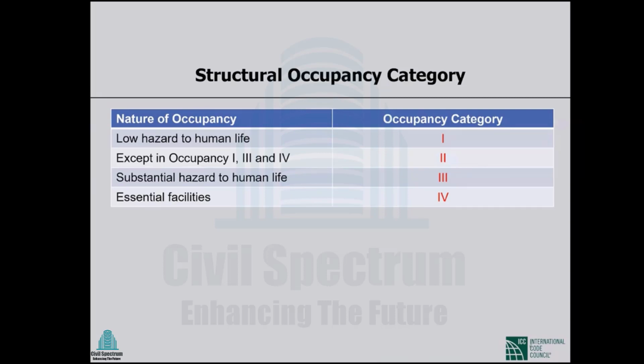For structural design purposes, the most important categorization is this, although the name is very similar to the architectural categories. That is also called building categories on the basis of occupancy. And in structural design also, we call it occupancy category. Basically, this is risk category. If a building collapses, what might be the risk? What would be the consequence of the collapse? It is related to this structural occupancy category.